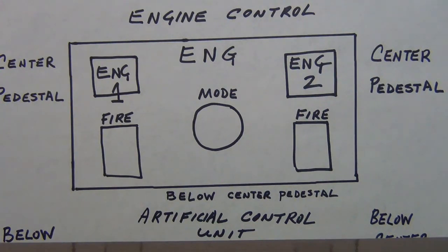And then your thrust levers, there are two, also on the center pedestal. With the thrust levers associated with that, you have your throttle, or your throttle artificial fuel unit, as well as a throttle control unit. Okay, so it pretty much gives you an idea there. Again, Rick's going to enhance this subtopic with a little piece to speak more conversationally to all aircraft maintenance technicians regarding the engine controls.